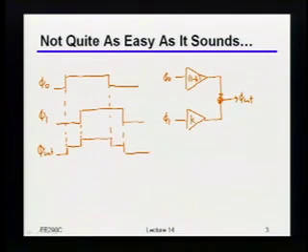If you connected a flip-flop to it, then it would trigger at either the first edge or the second one, or maybe somewhere in between. Yeah, basically you might very easily cause metastability, because you're sending some completely garbage analog level into the flip-flop. So you can certainly cause metastability.